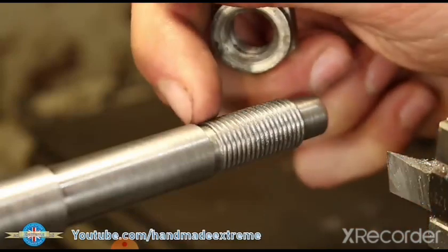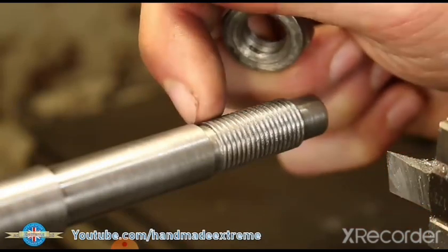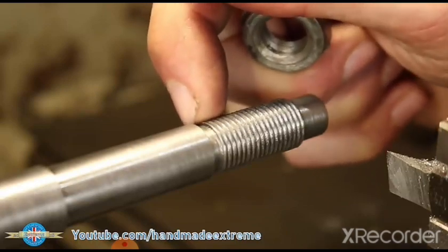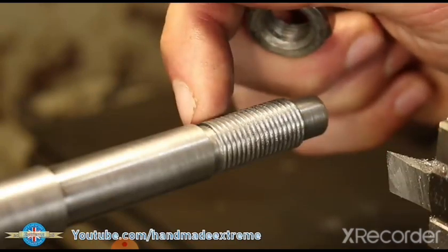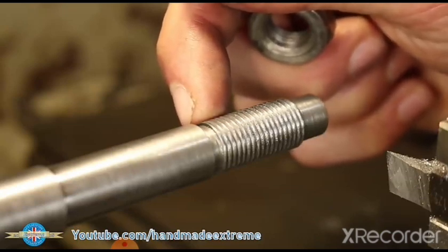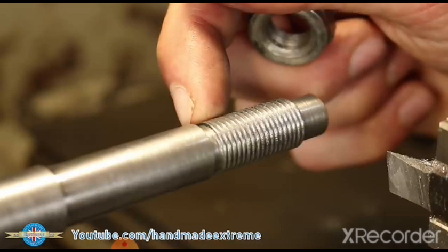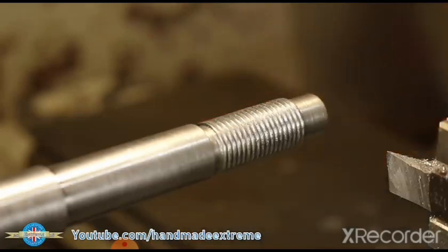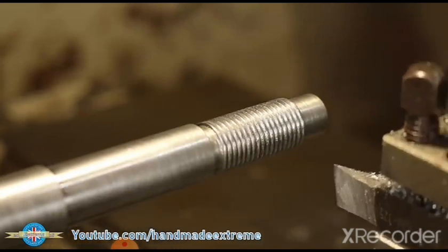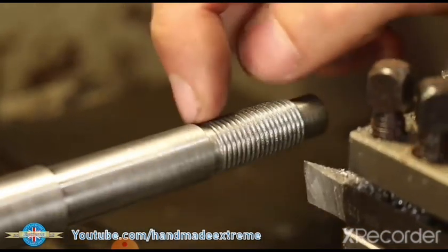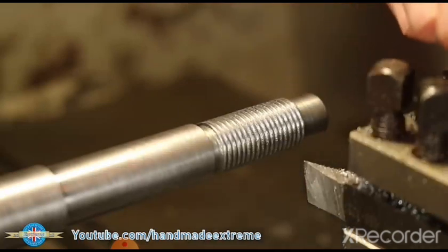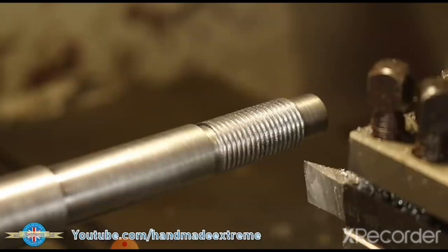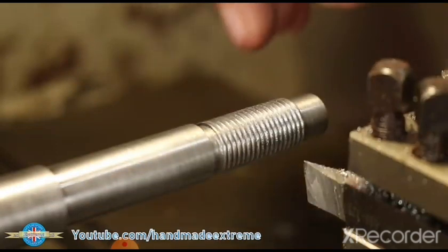But the problem I've got is I haven't made my gutter deep enough, and my threading tool is now starting to cut into the root of the gutter. Now, because we're using this method with disengaging and engaging the half nut, I've got a little bit more flexibility here. Using the really basic method where you drive the machine backwards and forwards, you can't do this because you'll lose your position. But because we're doing this method, I can now come in with a normal cutting tool, sort out this gutter, go back, put my threading tool back in, and with reasonable confidence, go back to the dial, and the threading tool should pick up and refine the thread.